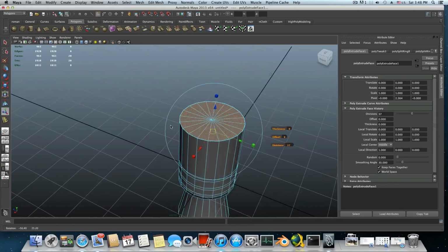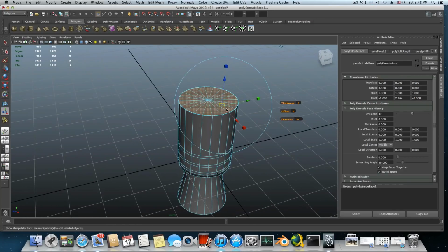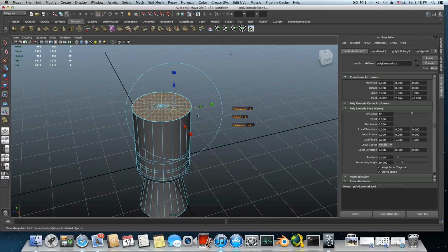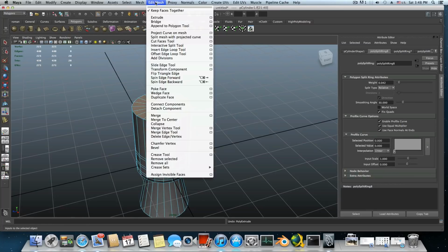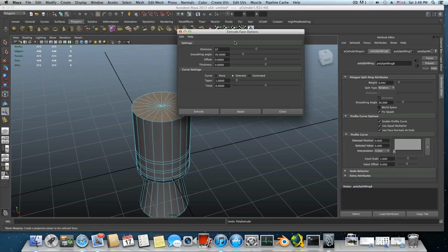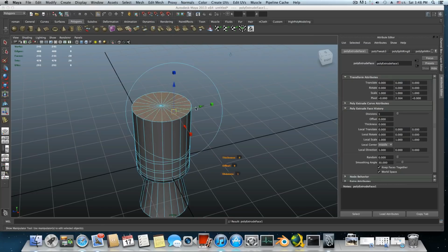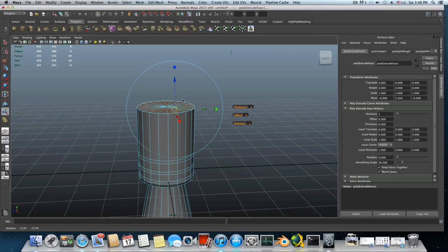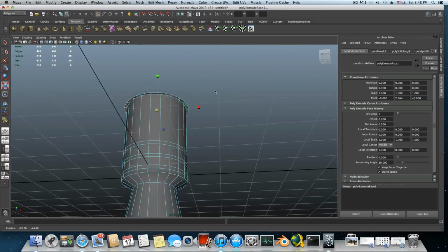outside, okay. I think, okay, no, don't extrude, just extrude it once, but no, I see what the problem is. My extrude tool is not reset, so I will reset the settings, and then I will extrude it. And here you want to grab, after you're done with the extrude, you click once on the scale tool and then open it like so, okay, so you'll get something like this.